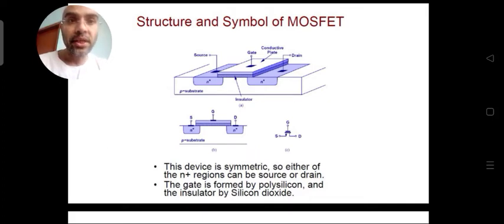And between the gate layer and the substrate, there is an oxide layer, which is SiO2. This oxide layer helps you to control the device as a voltage controlled device, and it will initially form a capacitor, because there is an insulating layer. On the top there is one layer, and at the bottom there is another layer. Two metal layers you can consider.